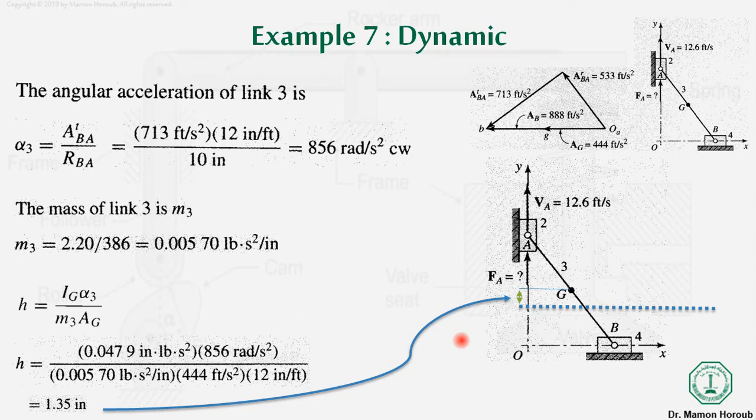So if you have these two conditions, one of the forces completely known, and for the other force only the direction known, that is, the line of action is known, then in the 3-force member you can calculate all the forces graphically. Okay, so here the known force is the inertial force.